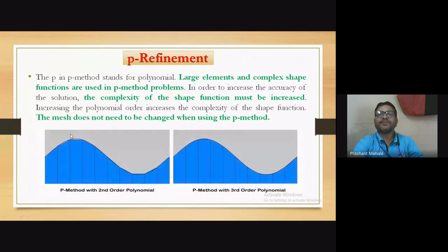So if I see here this straight line, can you see actually this curve resembles like a polynomial, but if you increase the order of element, this curve which is the polynomial before, you will find that it is touching the actual and very nearer. Can you see? So this is the analogous explanation and analogous understanding of this concept of P refinement.